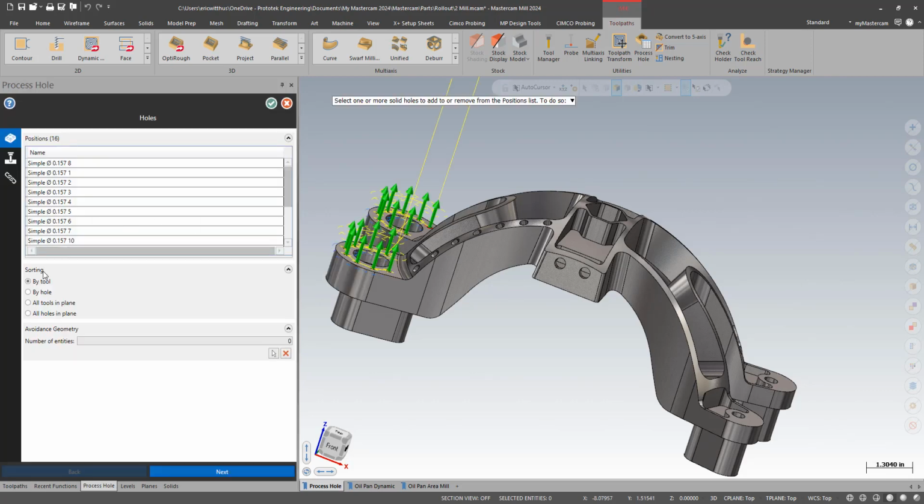There is kind of a cool sort function here too. If you're doing rotary work and maybe the rotations are slower than the tool changes, maybe you want to do something different. What I did there is spot drill, drill, drill. Maybe I want to spot drill, index. I can also change the sorting by hole. Since one toolpath does this all, I could easily just flip that and then it would spot and then drill, spot and then drill. If you wanted to do something like that in the past, it would take quite a bit of work. You'd have to make each one of those basically individual toolpaths. Now I can just flip a switch and change that order around.